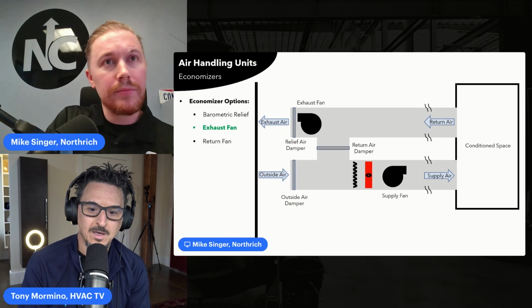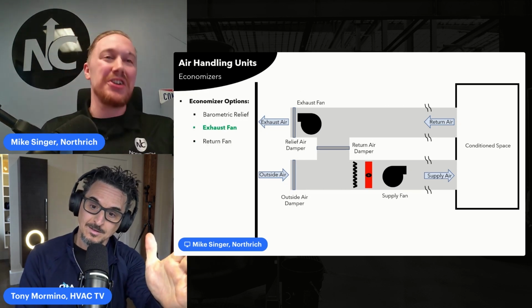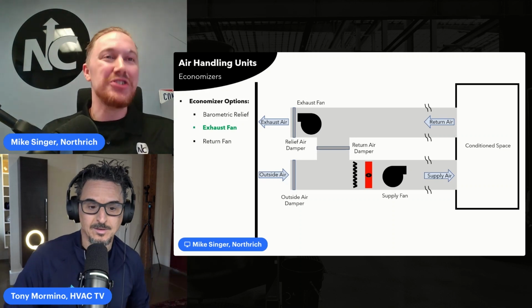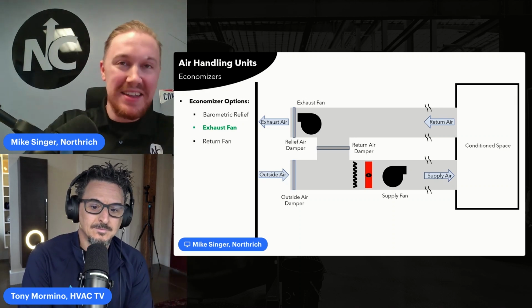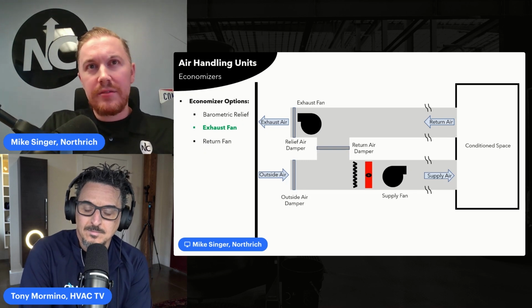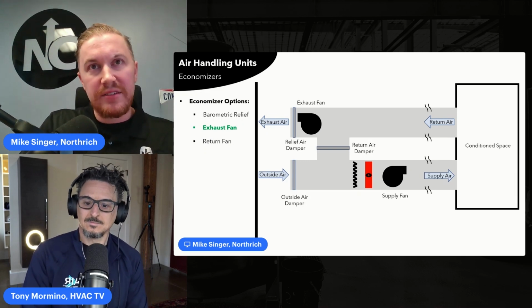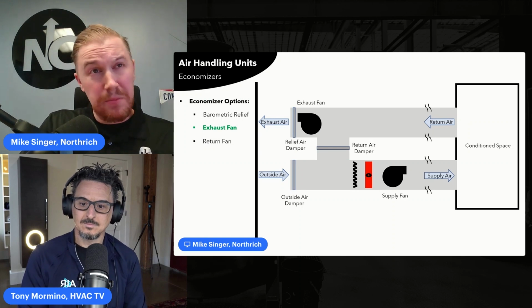Okay. I always think of it as the supply fan gets it to the exhaust fan. There you go. That's kind of like how my brain works. Yep, that's right. And we'll get a little bit more into control, but I always say that's the big takeaway. If we're controlling an exhaust fan, we're controlling it by that space pressure.